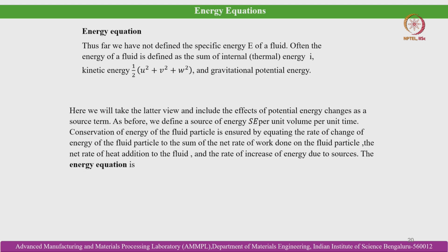As before, we define a source of energy, S_E, per unit volume, so here this will be the subscript, per unit volume per unit time. So, the conservation of energy of the fluid particle is ensured by equating the rate of change of energy of the fluid particle to the sum of the net rate of work done on the fluid particle, the net rate of heat addition to the fluid, and the rate of increase of energy due to the source terms.